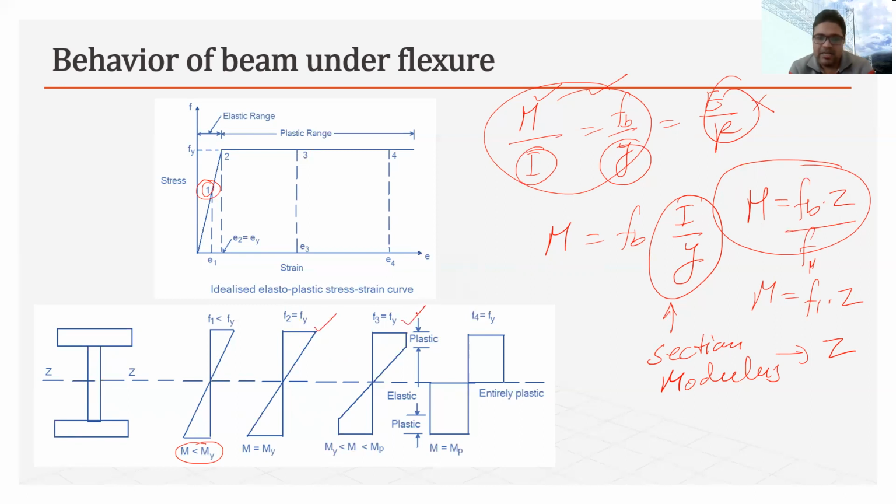Now in this it becomes plastic as well as elastic. So this part up to this part it is elastic, and this part becomes plastic. Now when we further increase the load, then what will happen? The stress will again increase inwardly. I mean, stress will not increase, but the same stress will reach the zone where the material is still elastic. So this increment of the stress will be inwardly, and similarly in this direction.